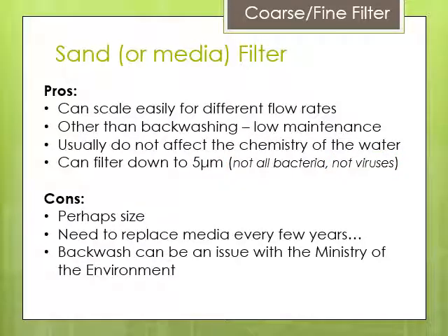Now, the Ministry of the Environment knows that these filters backwash, and they want to know what you're doing with that backwash. So it has to go into some sort of either a truck, right? Truck it away, and or it goes into a certified treatment facility. That could be a septic bed if it's sized accordingly, or it could be into an artificial wetland. We'll talk about that next class. There are some options, but just be aware that they're going to be very, very interested in what you're doing with your backwash.